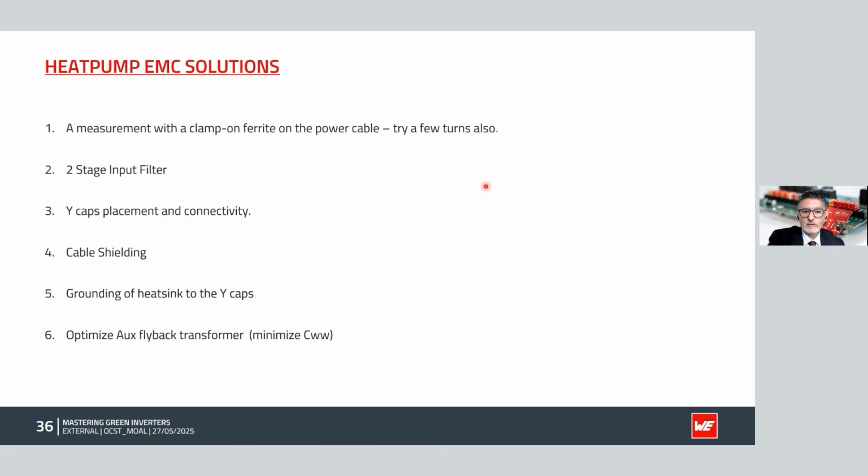As an overall sort of EMC improvements for that setup, what we have done is we have initially started off by using cable ferrite clamps on both the motor cable and the AC mains cable to try to identify what improvements need to be done and also what the noise sources are, whether it's these cables or something internal onto the board.